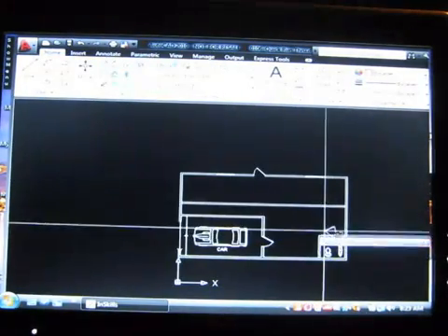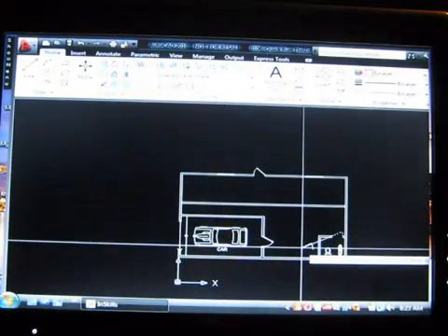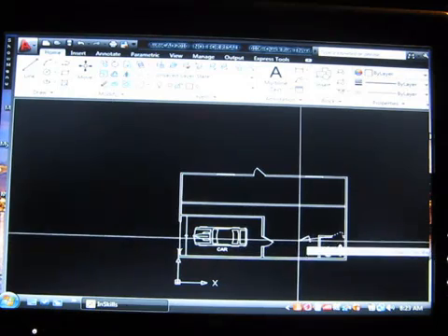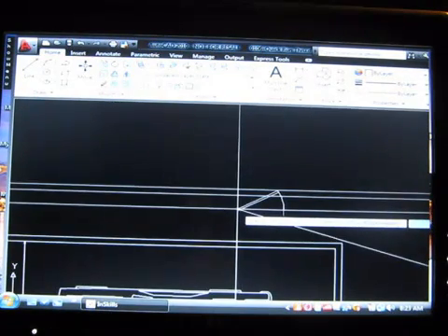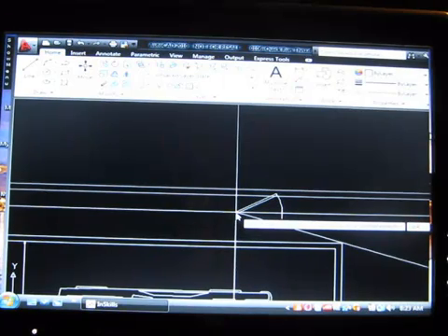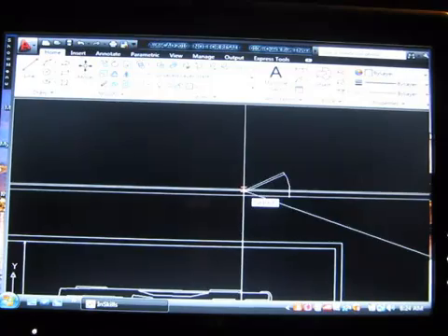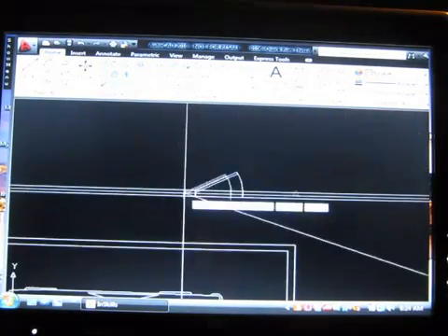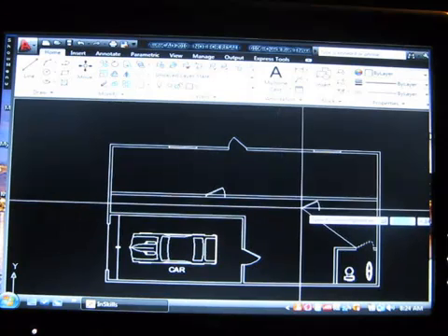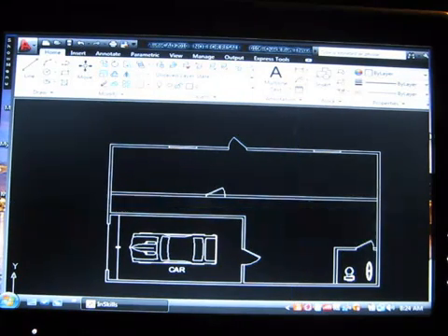As you can see, the door is not being moved, it's being copied. It will stay there. We're just copying it. Place it anywhere you want on the design. To do that, type in NEA, which is another snap point. It means near. It will put it near where you select on the other object. Press enter. You see a little hourglass looking glyph that comes up. That's where we want it. We're still in copy mode, so we could add another door somewhere if we wanted, but we don't. Hit escape to cancel out.